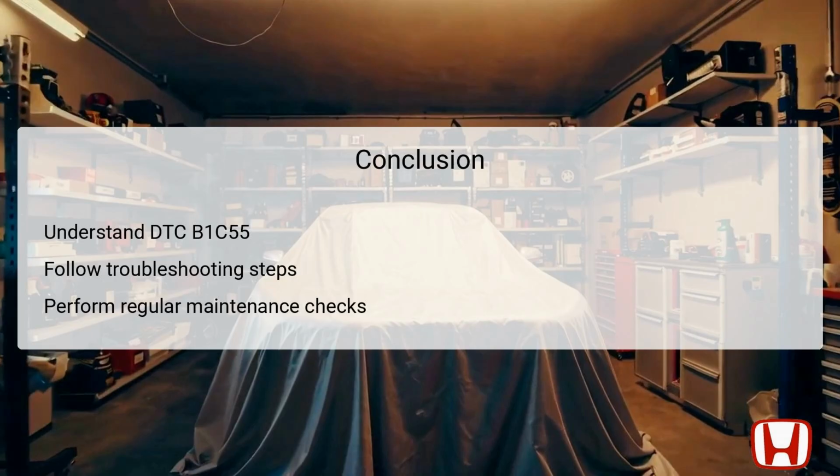In summary, understanding and diagnosing the DTC B1C55 is essential for maintaining comfort within the Honda Odyssey from 2011 to 2017. This error reflects an open circuit in the driver's heater thermistor, which is critical for the seat heating function to operate effectively. By following the structured troubleshooting steps, from clearing DTCs to measuring resistance, you can accurately determine the source of the issue and resolve it accordingly.